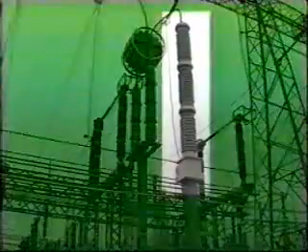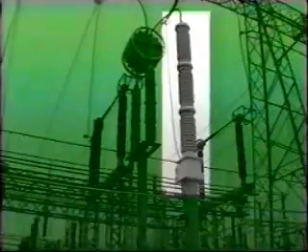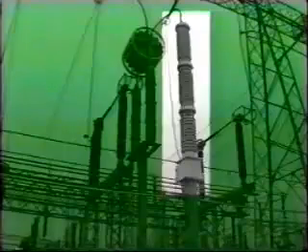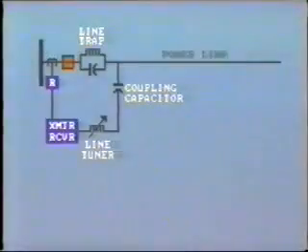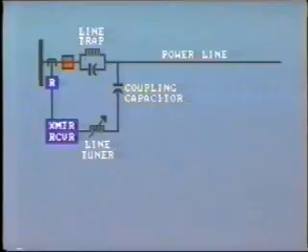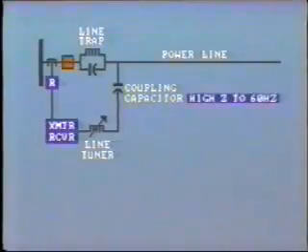This is a large high-voltage capacitor, which is capable of withstanding the power line voltage under both fault and switching surge conditions. This effectively provides the insulation of the high-voltage line at, say, 230 kV from the low-voltage transmitting equipment, say, 120 volts.